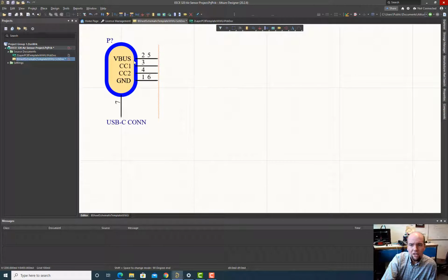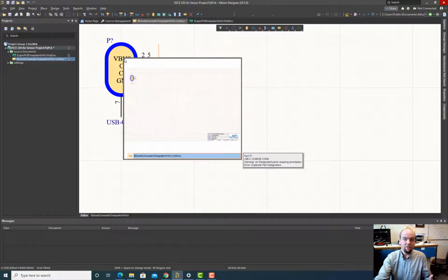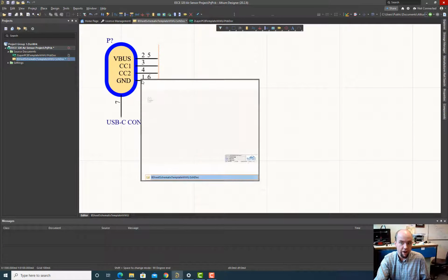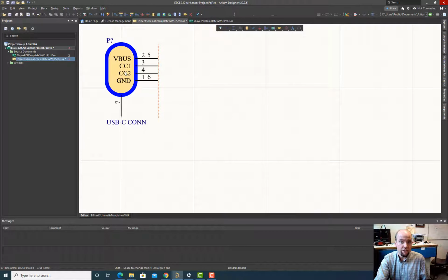This is pin 7. You see this pin, we have VBus, ground, CC1, CC2. There's 2 numbers on this VBus. So what this means is that this logical VBus, the pin that represents the bus voltage, should be 5 volts for USB. We have the pin that represents the ground for the USB. CC1 and CC2, we'll talk about those a little bit later. But when there's 2 numbers, it's saying that this logical pin corresponds to 2 physical pins. So there's 2 physical pins on the connector that are VBus, and 2 physical pins that are ground.